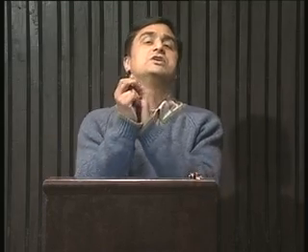We establish the control network. We measure it very accurately, so our skeleton is fixed. We can bring this skeleton into the laboratory, plot it. Now we work in parts. We measure the individual objects. And then while we are doing the plotting, we need to see about the scale. What scale is to be chosen? Well, one more question here. How to decide about the scale?